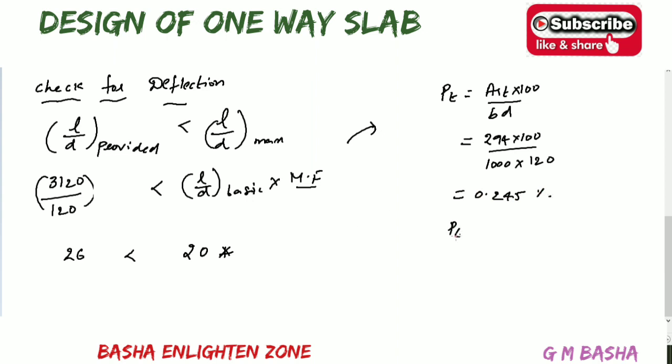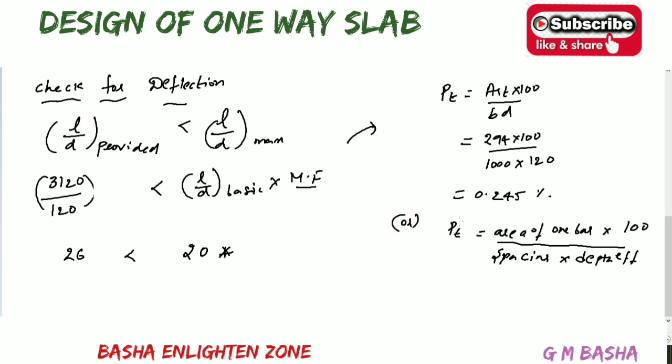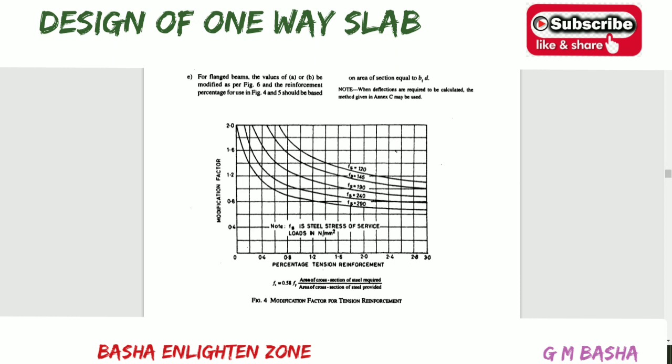For calculating this Pt there is one more formula: area of one bar into 100 by spacing into effective depth. You can calculate either way, whichever is convenient. Based on this percentage, 0.245, if you observe the axis, it is 0 and 0.4, so 0.2 is approximately here where I am showing the cursor. So you will get a percentage tension reinforcement of 0.245.